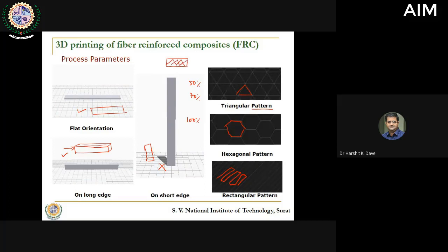I'm just trying to show. And the rest of the space between the polymers, between the fibers, remains vacant because you have ensured a smaller value of density. So these types of patterns work well when you need to reduce the density, and when you reduce the density, you reduce the consumption of material as well as the time for printing. Even with such lesser density, you are able to get better strength as compared to other competitive